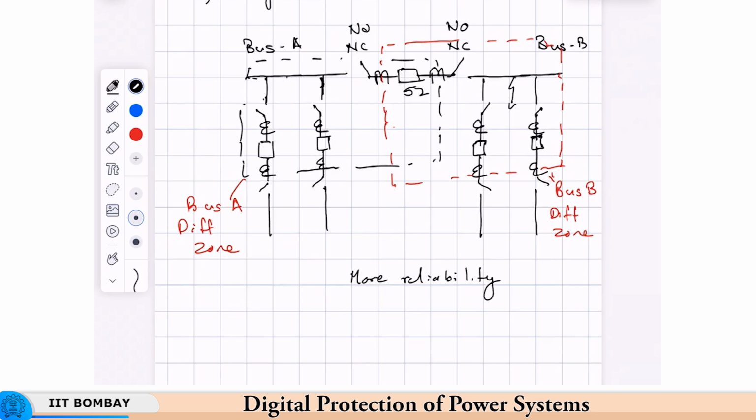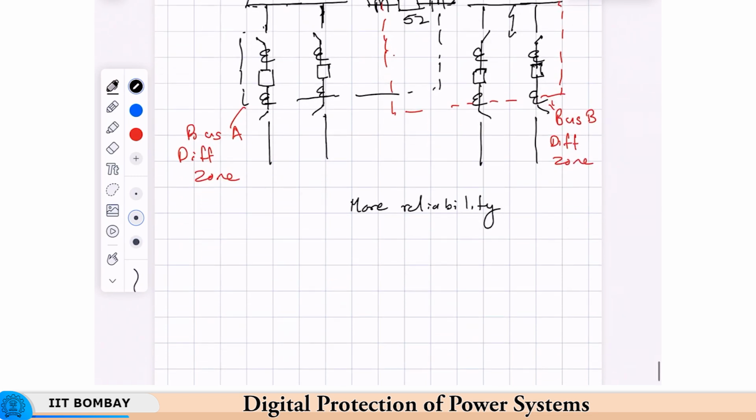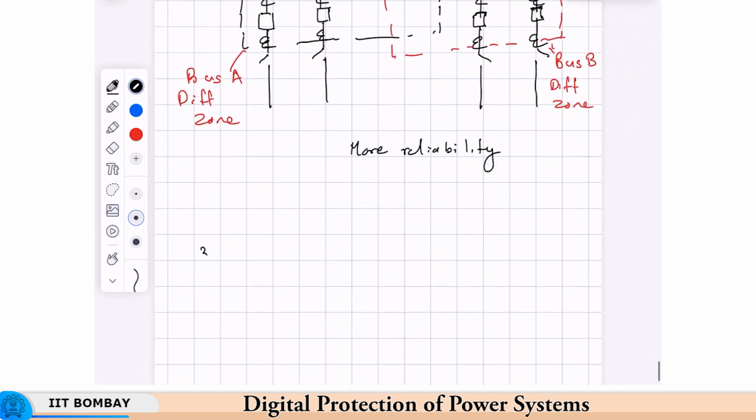Okay. There is one more scheme involving the single bus bar. For having complete redundancy, you will need 2 bus bars, so that if there is a fault on one bus bar, that bus bar is taken out of service, but supply continuity is maintained through the other. So, those involve 2 main buses, main 1 and main 2, but before that there is another type of arrangement known as single main or single bus and transfer scheme.